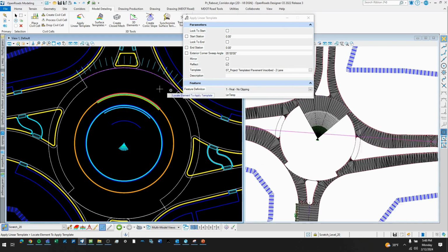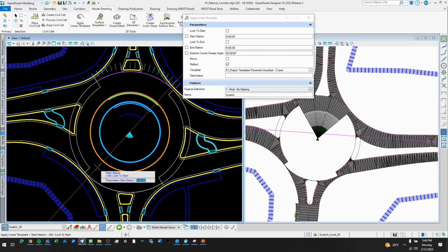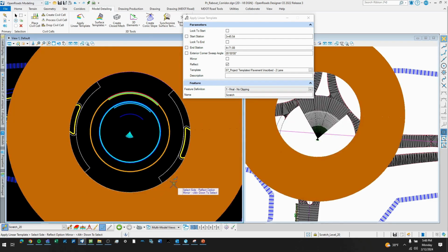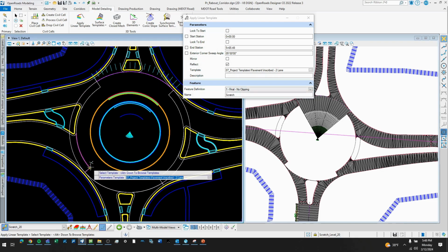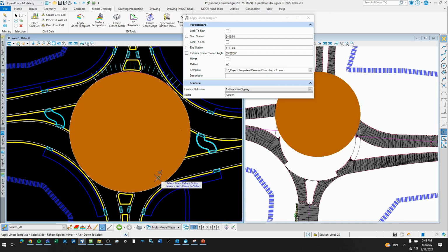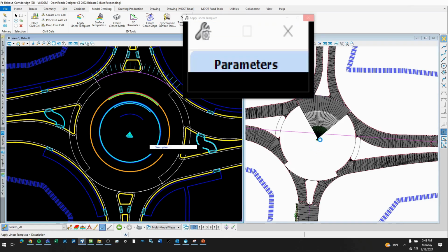So that looks pretty good. Pretty happy with that. So we can do another one. We'll keep the same. We'll do the other 2-lane one. Starts on this end, that section to that section. I might have messed that up just a little bit. I'm going to click out. Try it again. 2-lane. Let's see if I can get the snap right. There we go. That looks right. Hopefully that's another piece of the pie. There's a little bit of overlap here, but it's not going to be a big deal. This stuff is good for earthwork calculations and stuff on that embankment.